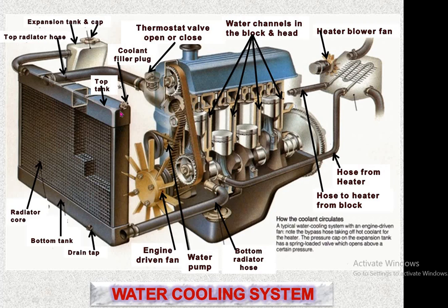Then the coolant filling plug, from which we can fill the water in the upper tank. This is the top tank in which we can generally fill water as a coolant, or in cold regions, as I have told, certain coolants are used instead of water. This is the expansion tank and cap. Due to the high temperature there may be water vapor, so there may be expansion of the volume. In that case this expansion tank is employed to accommodate the water vapor as well as the volume that has increased due to the high temperature.